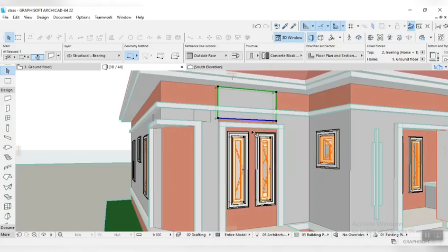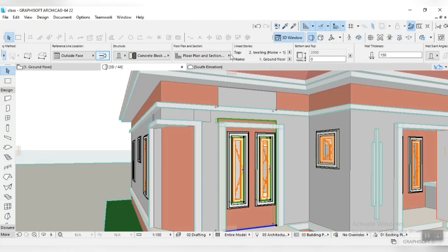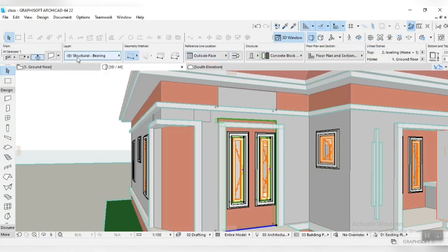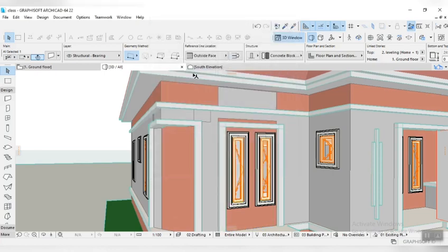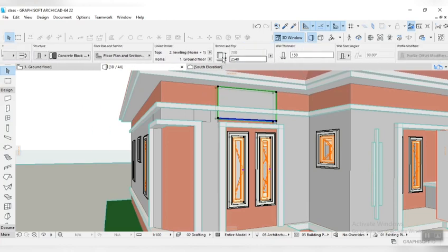I'm going to correct that, guys, don't worry about this. First, let's change this wall. We have 2.8 meters and we're looking for 2450, so automatically we minus 2450 from 2.8 meters. That's going to give us minus 350. Let's see what we have there. 2450. Let's check it. Okay, perfect. So let's bring this to bottom offset 2450.